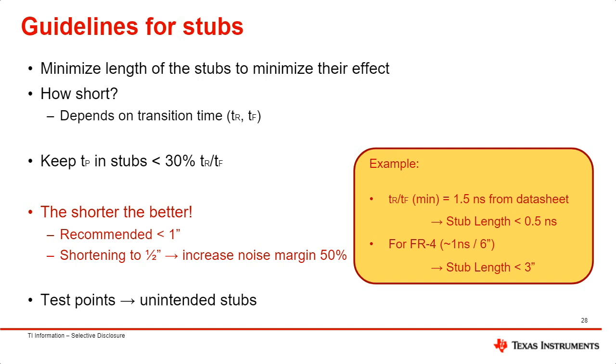If you were to use a standard like LVDS for multi-point, your rise and fall times are much faster, which enables higher data rates, but that would severely limit the stub lengths that are supported for multi-point. So MLVDS just gives that additional flexibility within the standard to have longer stubs. But if you can, it's best to minimize the effects by making them as short as possible.